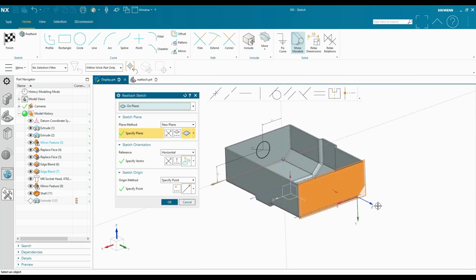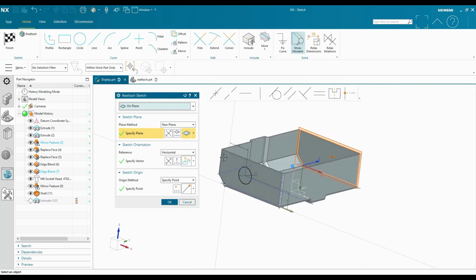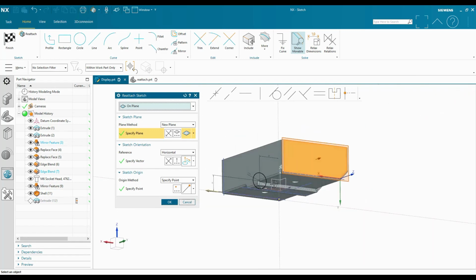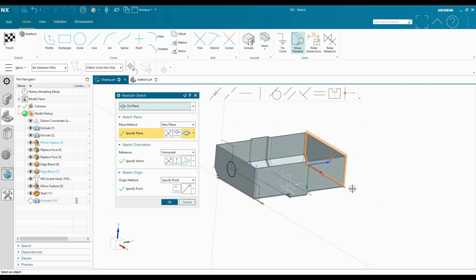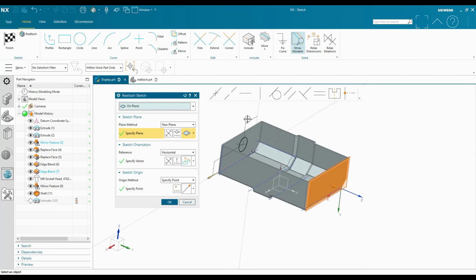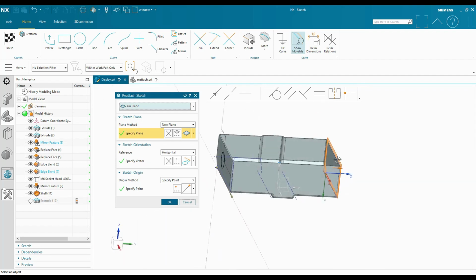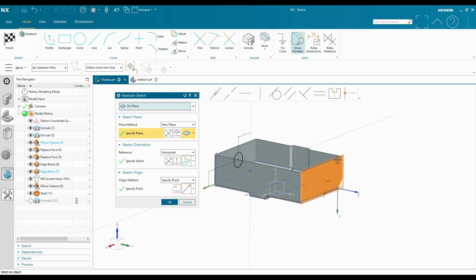Now, I do need to pay attention to the orientation here. You'll notice that my X, Y, and Z is a little bit different. I'm probably going to put those curves somewhere else relative to that XYZ because of the dimensions I was using in the previous sketch. So I could delete the dimensions, reposition that, and then add some dimensions.